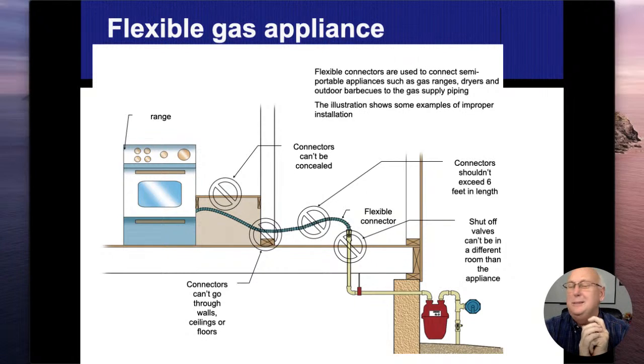All right. And I don't think they sell gas connectors longer than 6 feet anyway. I know you could buy CSST stuff, but not gas connectors longer than 6 feet. We can't daisy chain them. So I can't take one 6-footer, put a fitting in between them, and another 6-footer to reach my appliances. Maximum length 6 feet. Even if I get two 2-footers, and that's only 4 feet, which is still under my 6-foot mark, I can't do that either. So we can't daisy chain these things together.